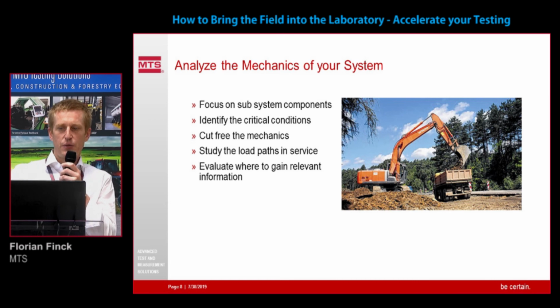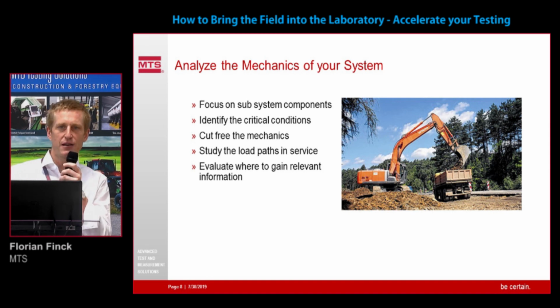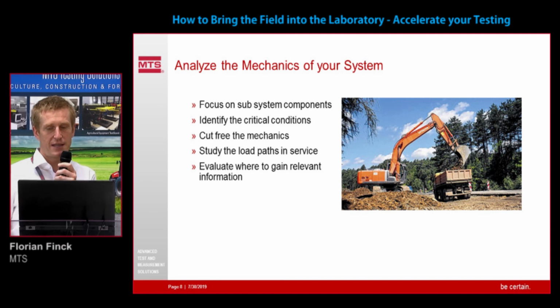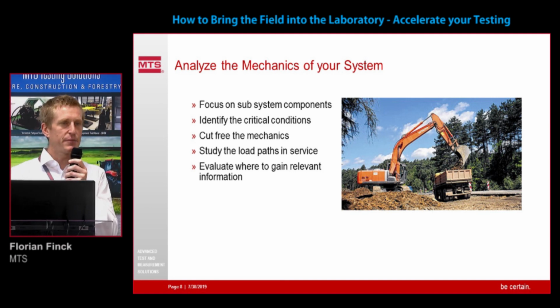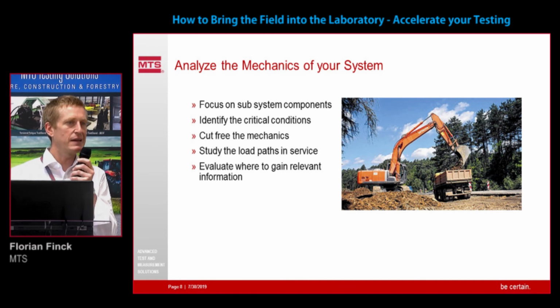And then maybe when you see this two-dimensional problem, you're looking at the loads, but what happens when the whole excavator is making turns and stopping? There's a side load on the whole structure, which will also cause damages. Also the ambient conditions: when the machine is moving in the ground, there's a difference whether it's dry sand or wet soil, or maybe it's even winter time and the soil might be frozen in some areas.